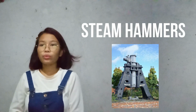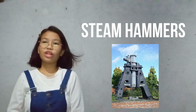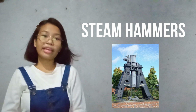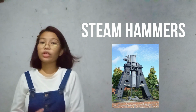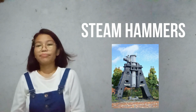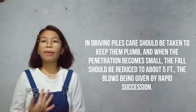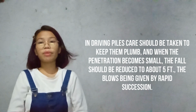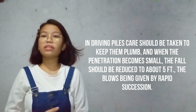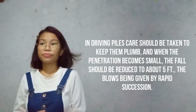Steam hammers are to a considerable extent taking the place of the ordinary drop hammer, as they will drive more piles in a day and deliver quick, short blows from 60 to 70 per minute. In driving piles, care should be taken to keep them plumb, and when the penetration becomes small, the fall should be reduced to about 5 feet, the blows being given in rapid succession.